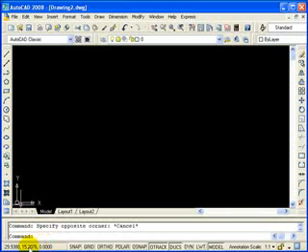At the very bottom, on the left hand side, in the bottom left hand corner of your status bar, you'll see your coordinates, and what that is, that's the coordinates of where the crosshairs are in the Cartesian coordinate workspace, which we'll touch on a little bit later. There's some options here for turning on some of the AutoCAD options as you're drawing. You can click on these as you're working. O-snaps, ortho, and things like that. We'll get into some of these other options as well.